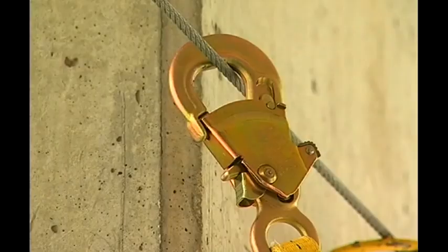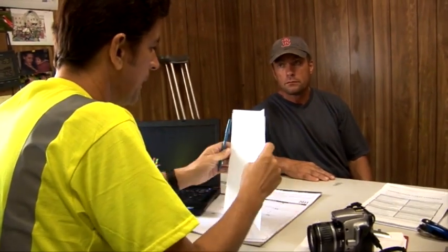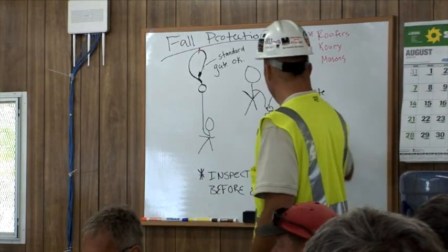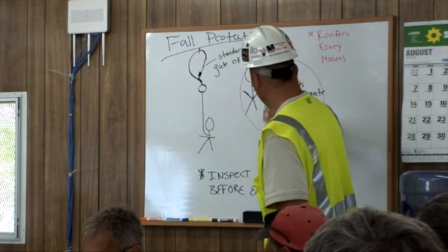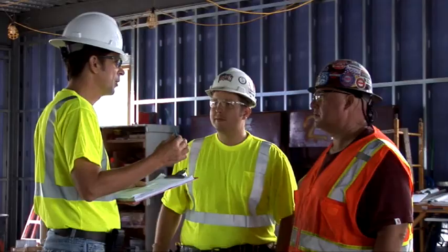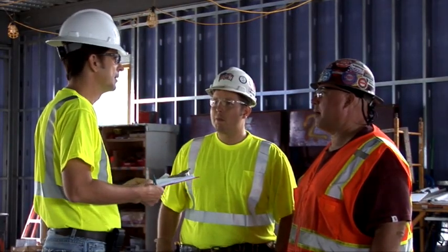platforms. An anchorage must be capable of supporting 5,000 pounds per employee attached, or be designed, installed, and used under the supervision of a qualified person as part of a complete PFAS, which maintains a safety factor of 2. A qualified person is defined as one with a recognized degree or professional certificate with extensive knowledge and experience in the subject field. The person is capable of design, analysis, evaluation, and specifications in the subject work, project, or product.